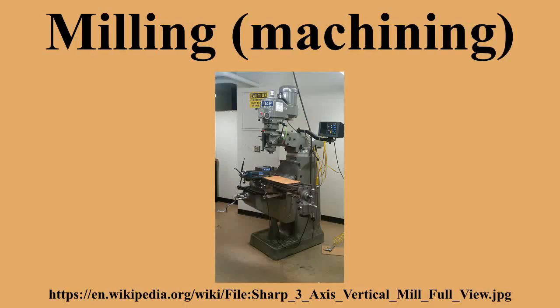Milling cutters. Many different types of cutting tools are used in the milling process. Milling cutters such as end mills may have cutting surfaces across their entire end surface, so that they can be drilled into the workpiece. Milling cutters may also have extended cutting surfaces on the sides to allow for peripheral milling. Tools optimized for face milling tend to have only small cutters at their end corners.